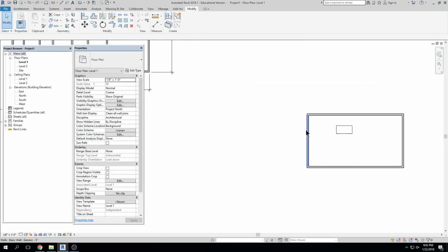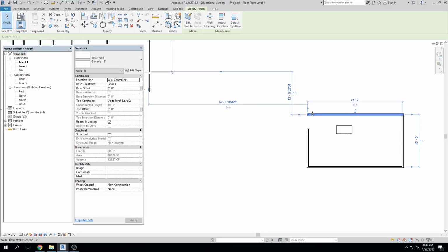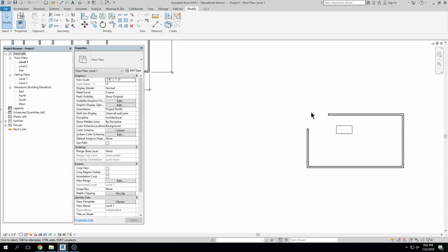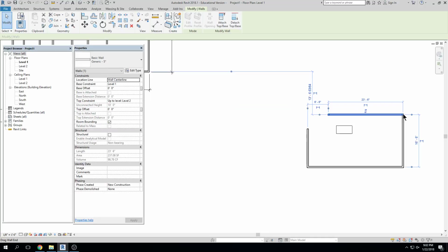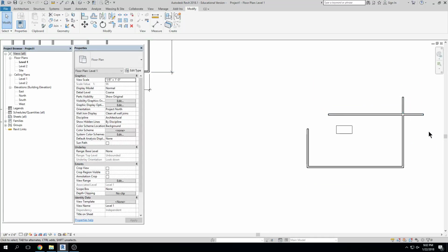Now the key to trimming in Revit, I'm going to undo these, undo, undo, undo, Control Z. Let me just say this: when you're trimming something, whether it is like this where they don't meet or one object extends past the next, you're going to use trim. There's no trimming, extending type stuff anymore. TR, trim, click, click, right? Click, click. There we go.